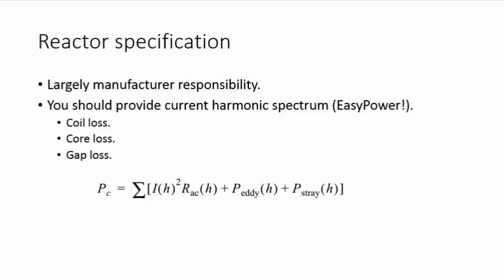The reactors are very sensitive to heating because of harmonic content, because in the core you have an eddy component, an eddy power loss, and it goes bigger with bigger frequencies. When you expect harmonic frequencies to flow into the reactor, they will overheat the reactor because of eddy core losses. So the reactor should be prepared for it.